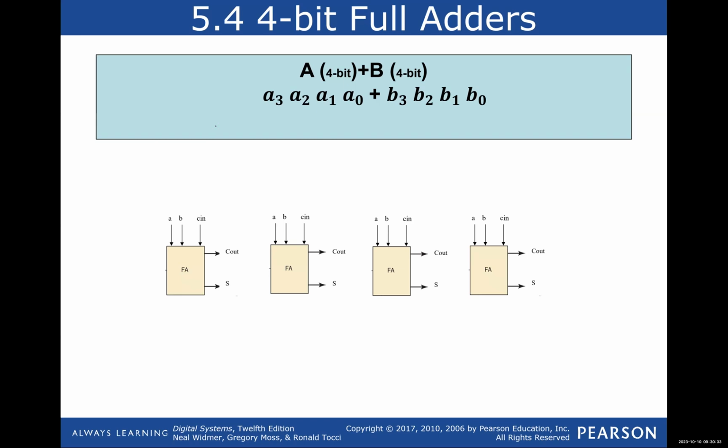You're going to say, for example, standard logic vector, 3 down to 0, and that is, for example, your A. So your A is a vector of 4 bits. Your B is another vector of 4 bits.